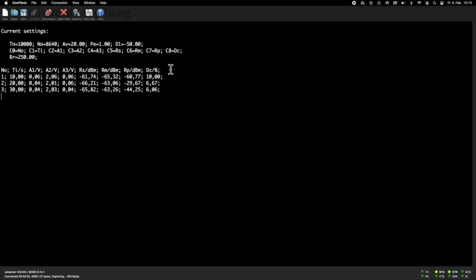It is recording the RSSI measurements and the duty cycle, as well as the voltages on the analog inputs, where I connected a little solar panel. This is only for test. The voltage on A2 is basically telling us whether the light in the room is on or off.